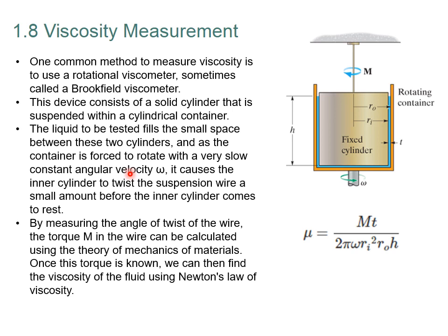So how do you measure viscosity? Well, the common way you measure it is to use what's called a Brookfield viscometer. You can look online; there are several good YouTube videos of the Brookfield viscometer. It's basically a cylinder within a cylinder, and here the blue is your liquid you pump in.